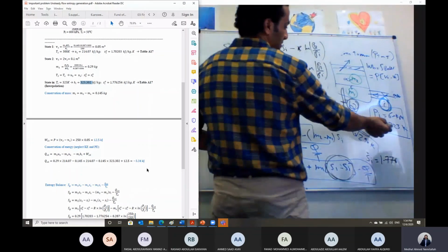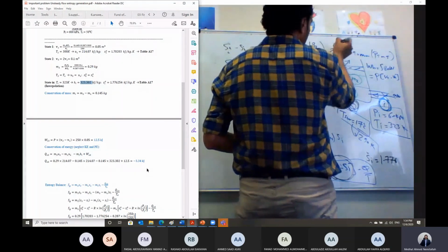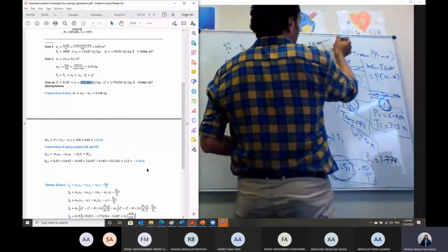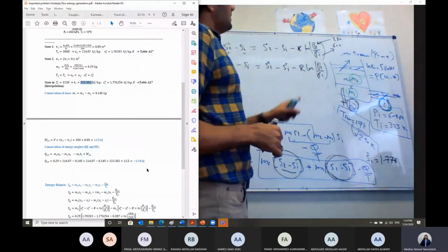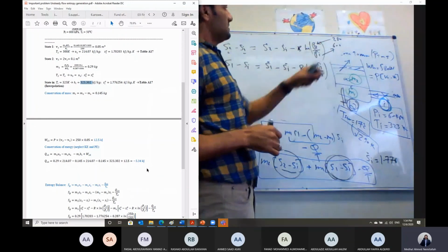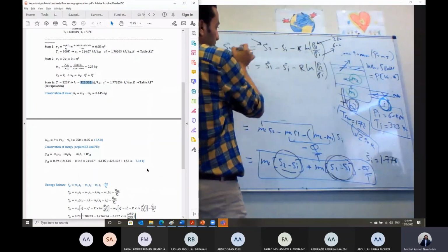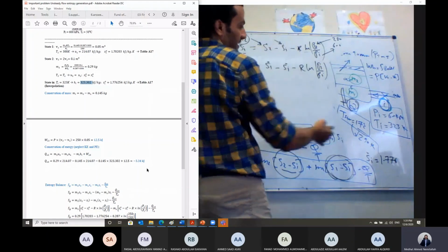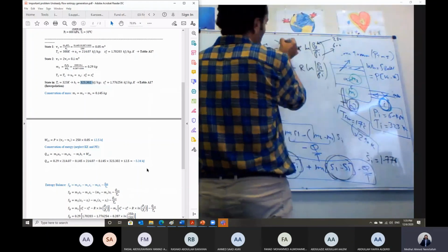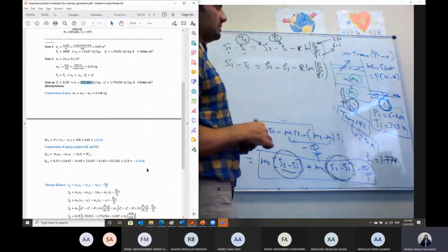We have the inlet pressure given, P inlet is equal to 600 kilopascal, and we have P2 equal to 250 kilopascal. So ln of this number, less than 1, will be negative. Then S naught 2 we just got from table A17 at temperature T2, and at the inlet temperature we got this value also from table A17.